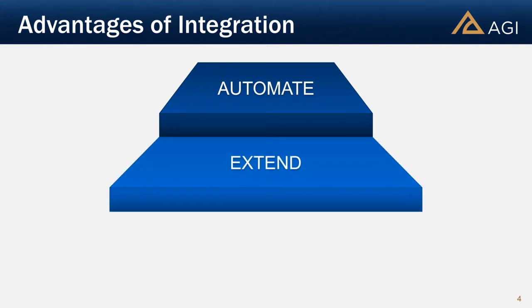Next, you could also extend or augment the types of analysis that you can perform with just one of these tools. For example, you could use the STK satellite propagators in your study, but you might have a custom sensor, so you would create and define that and then push it into the STK model. And if you wanted to post-process it, maybe the type of component you wanted to create is something a little different than the 40,000 metrics, but then you can post-process it in MATLAB or Python or whatever else with the STK-generated data.